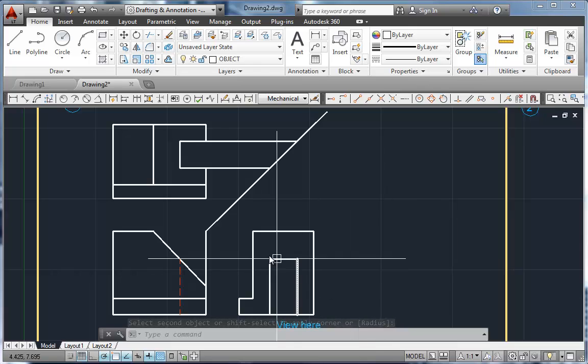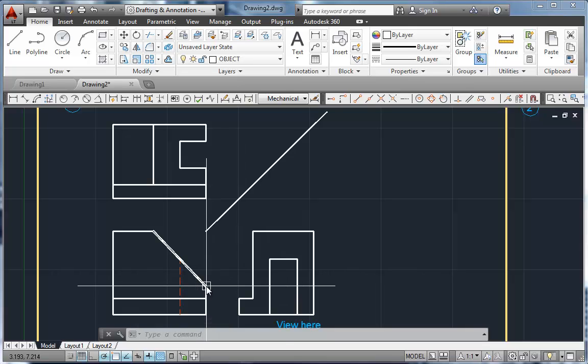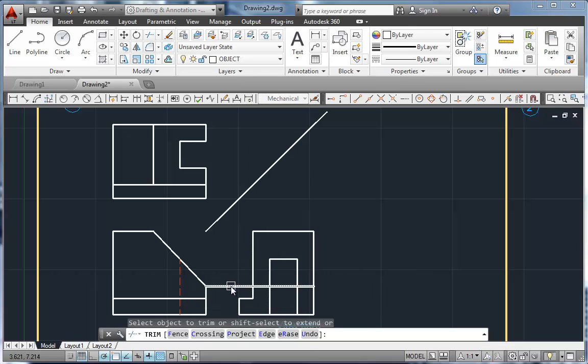Now I'm missing one more thing. Let me take this line out to clear up that space. We'll take these out too. I have a corner right here. That corner, if I look in the top view, runs across here and across here. So I need that corner in the front view, so I'm going to do a line. I'll take it all the way across, and then we'll trim, and we'll clean out those two. That corner is broken in the middle because there's nothing in that space right there. It's empty space. That corner is interrupted. I have no hidden lines, so this is my finished drawing.